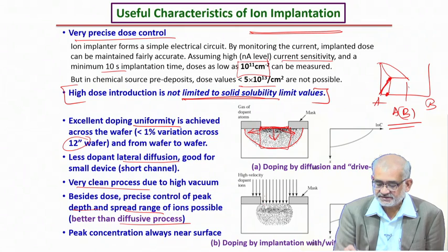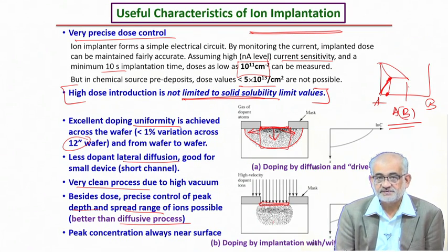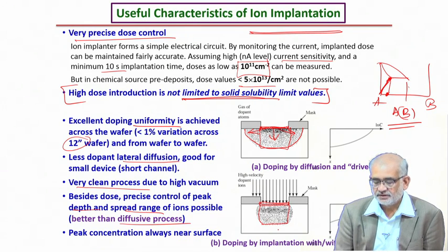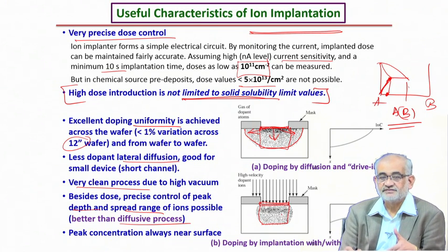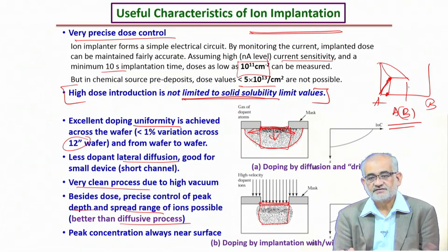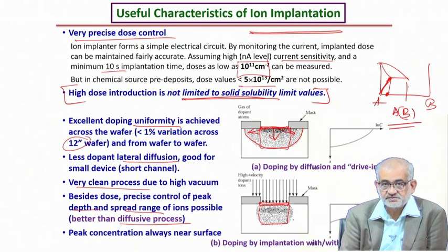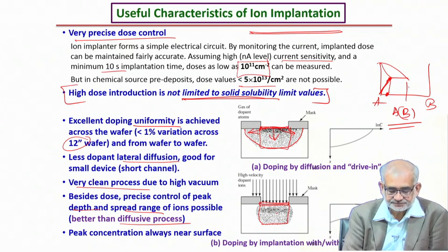In case of ion implantation, which is a directed energy implantation, you initially form a dopant concentration up to a shallow depth, and in subsequent annealing, when you allow the species to diffuse, there will be some amount of lateral diffusion, but generally the profile will be fairly close to the targeted range. That means the precision of the performance or the properties of the substrate will be better controlled here.